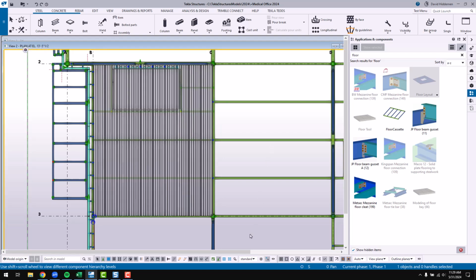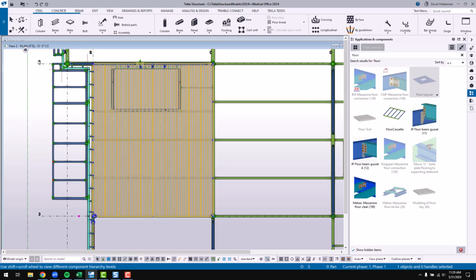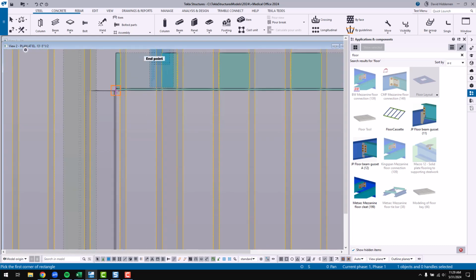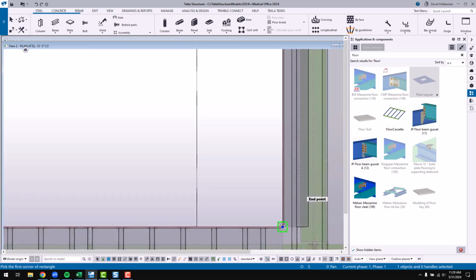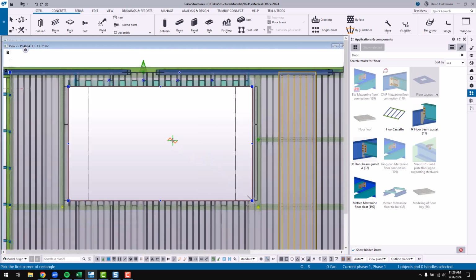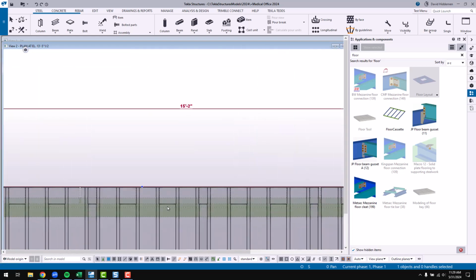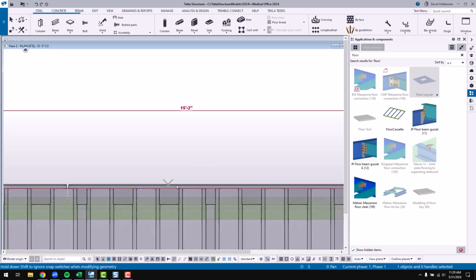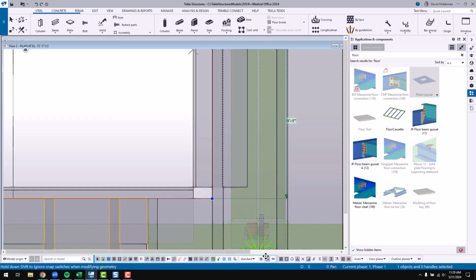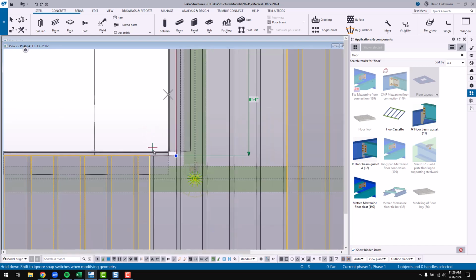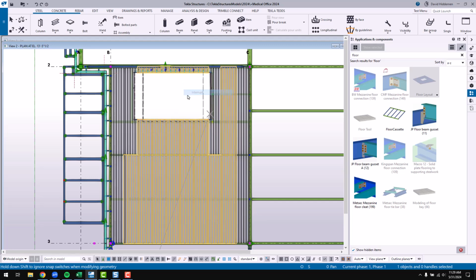Also in here, let's go ahead and change my selection back to selecting components, is the same sort of rectangular opening. There's also a circular opening in here. So I can activate the rectangular opening, and then I can rough in this opening that's here for a stair or an elevator shaft or something like that. And now this opening is an element that I can continue to modify using the push and pull functionalities, the drag and drop stuff in the direct modification function. So very, very powerful stuff.